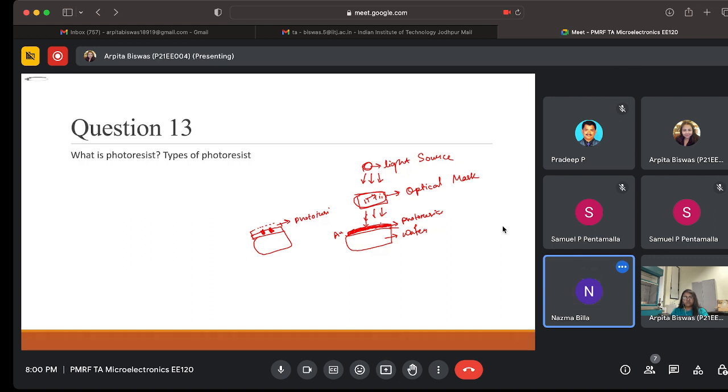Okay, it is a little bit true, but at first when we are exposing to light, there is a photosensitive layer. Photoresist is a photosensitive layer. If it is a bright field mask, this is the opaque portion, so only this opaque portion will remain. You give the UV exposure, and the mask is transparent elsewhere.